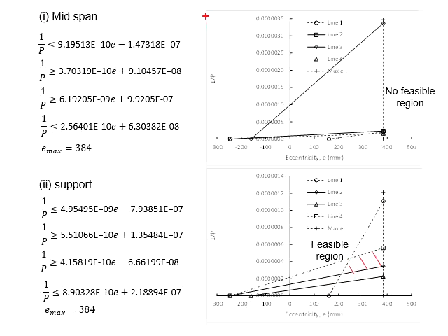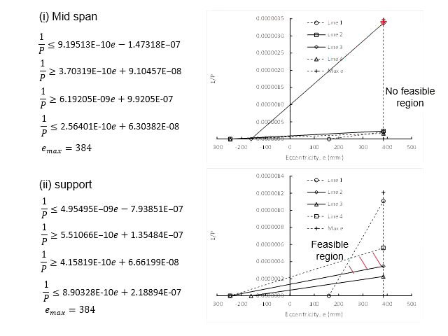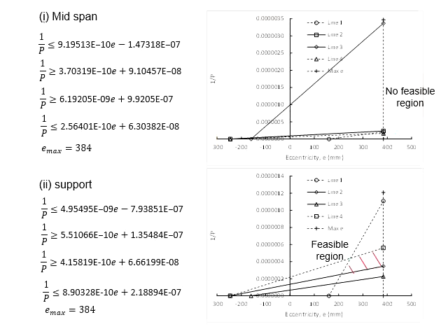If you observe the Magnel diagram here, the feasible regions as indicated by this line will be greater, and the feasible regions as indicated by the line here is also greater. However, the other two lines below this line is lesser. You will see that there is no overlapping regions between the lines here. That means there is no feasible regions for the midspan.